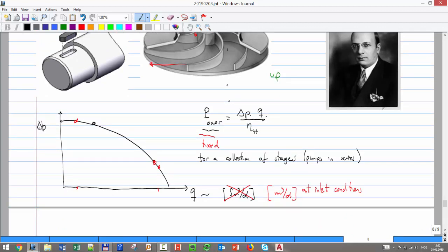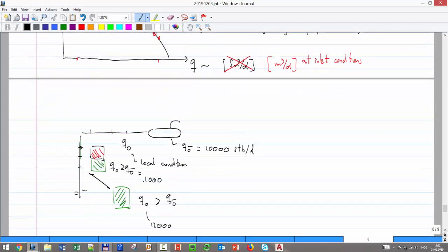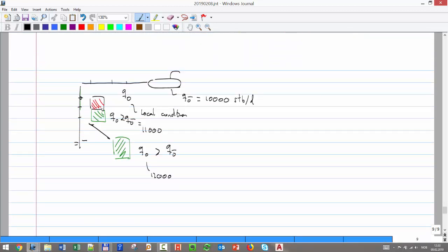Now that equation, typically we use the pump equation. We have delta P of the pump equal to the density of the mixture. You might have water, and actually in the exercise we're going to have water. And then that times an equation that looks something like that: A Q, B Q, with some coefficients.